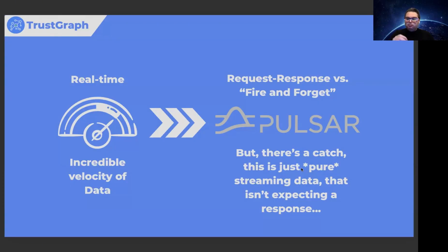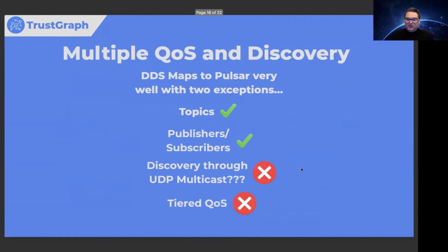That's where we run into some really, really interesting challenges, though we could absolutely map all this stuff. So if we take DDS pub/sub, I could go into a little bit about DDS right now. There are differences. It's a publish-subscribe system that's going to run on deployed applications like a car. I know a lot of autonomous vehicle manufacturers actually use DDS on vehicle. Very, very common in aircraft, drones, etc., where you have federated networks and you have quality of service requirements.